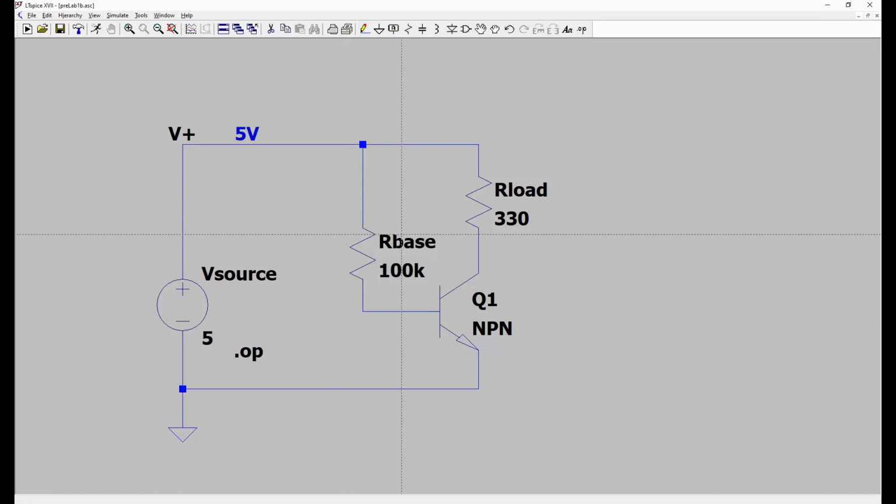I'm going to bring a line out, and I'm going to call this V out. Right click, label net, V out, and attach it to the line. I also want to see what the real-time value is, so we can immediately right click, place a data label, which hasn't been calculated yet, at least not as V out. It was calculated as one of the N1 or N2, but we don't know which for sure.